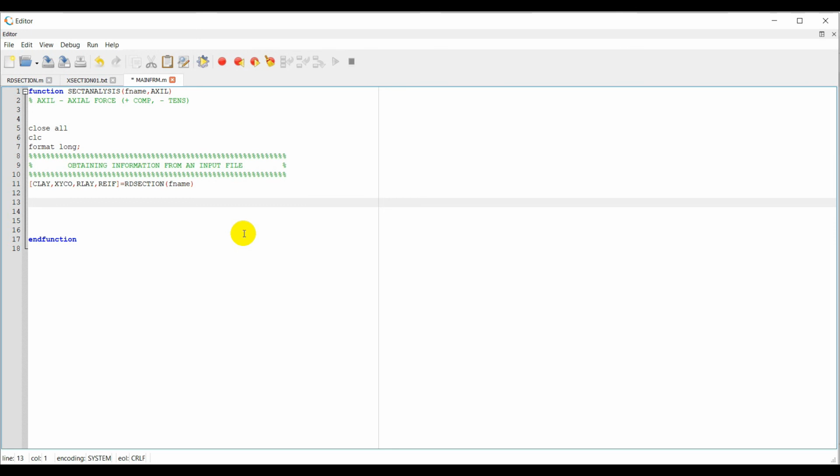So curvature has to be specified because we're going to have the moment versus curvature plot. So we're going to put many different curvatures. We keep adding in the curvatures. Okay. So what is the limit? That will be our job to figure out. But now we need to make the routine that works for one curvature.